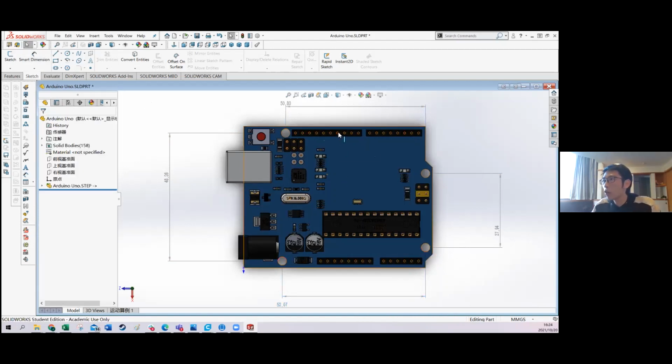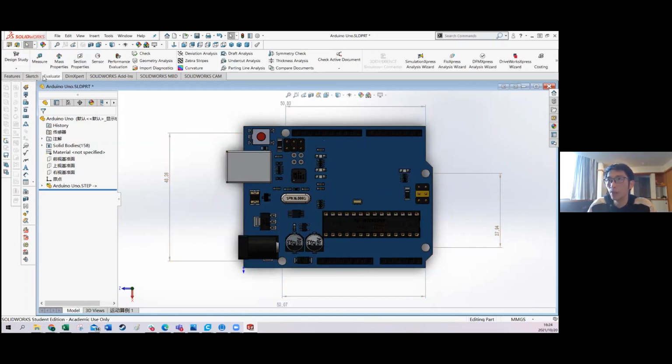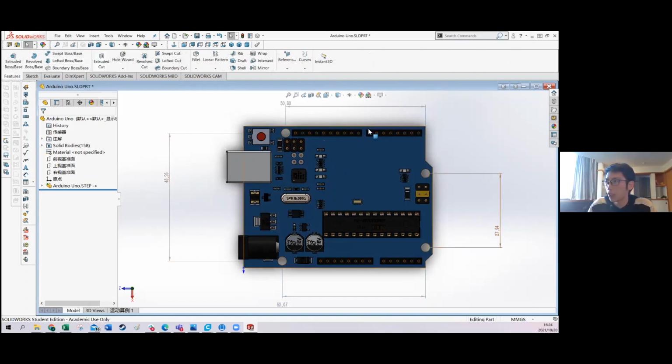Great. So when you've got all those dimensions, you can just open a new part, and then it's all some basic features. You open a new part, you go to Sketch, and then you use an extruded cut feature to cut the 4 holes on the chassis. But I feel like this might not be the best way you should learn, because it's kind of dependent on the part that the user created. If he didn't make it that accurate, it might affect it when you manufacture it, because after all, you are the person using the chassis that you make.